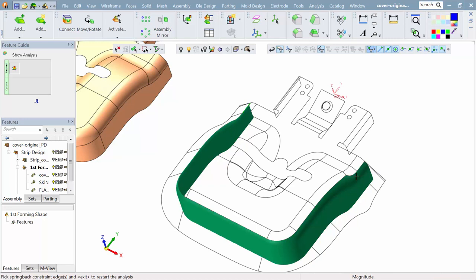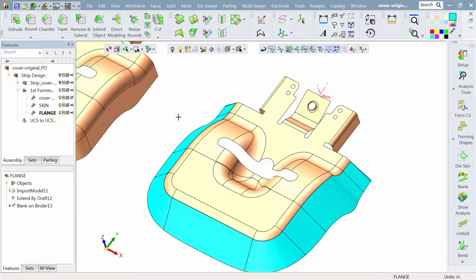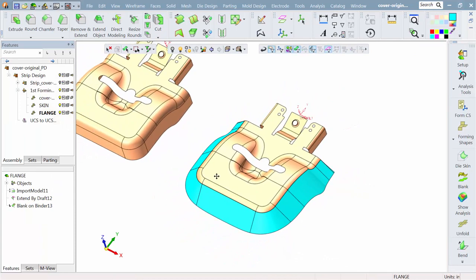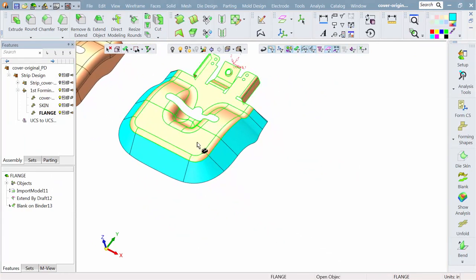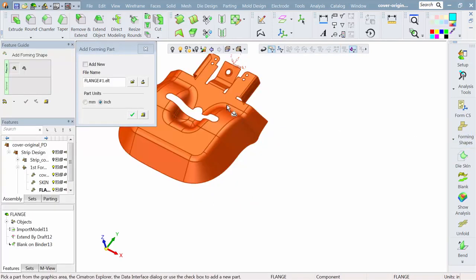Also, we can set this up so that we can look at some spring back. I'm picking a few areas. I'm saying hold on to that and let's see what possible areas of spring back may develop. It's based upon just that hit, just that development to 45 degrees. And there you saw in red an area that may show some spring back on the edge. We can take that information much further and actually adapt the forming tool to compensate for the spring back as well.